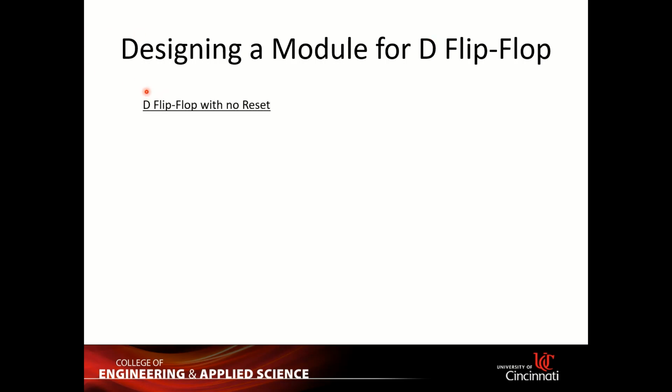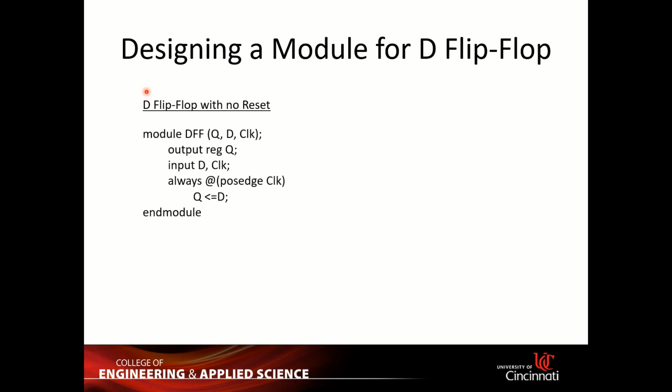First we design the D flip-flop with no reset. As you remember, you start with module and endmodule. You give it a name, everything is the same. You put in all of the necessary pins. There's no reset, so there are only 3 pins: you have the data input, you have the Q output, and you have the clock. So the output, let's just call it Q.